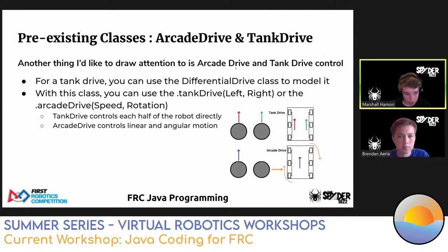The alternative is arcade drive, where you have one joystick's vertical position correspond to the linear speed of the robot, the absolute speed of the robot, and the other joystick's position correspond to the rate at which the robot rotates. So they can be integrated into either one or two joysticks. In fact, the main advantage of arcade drive is the fact that you can incorporate it into one joystick, leaving the other one occupied for some other mechanism. Otherwise, you see tank drive used more often because it gives you more direct control of the robot.